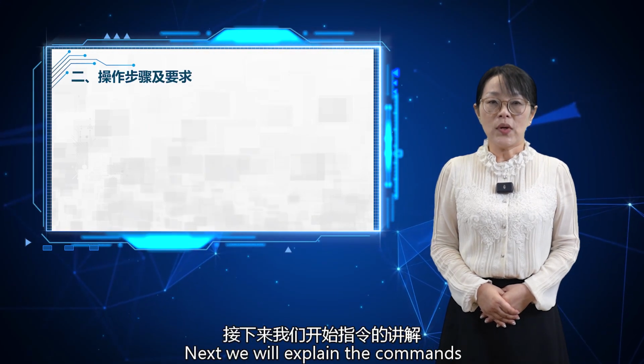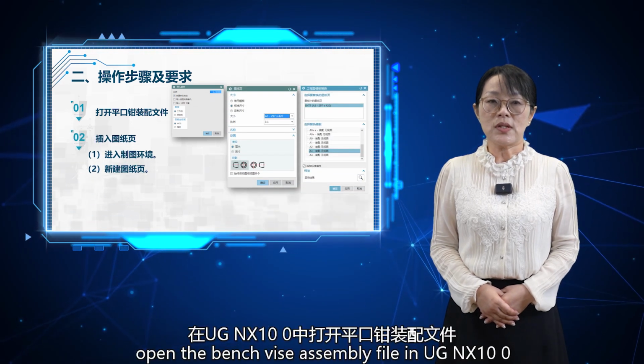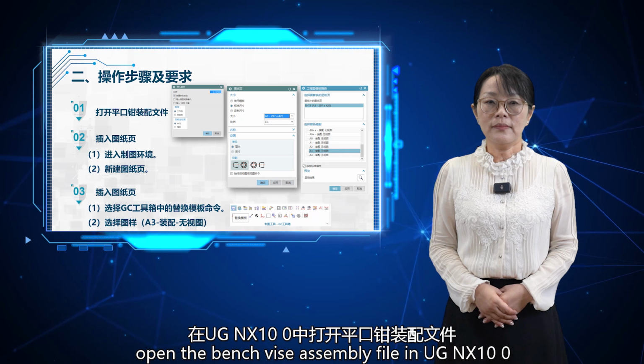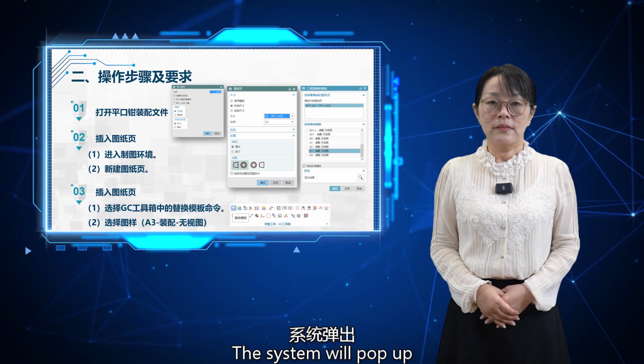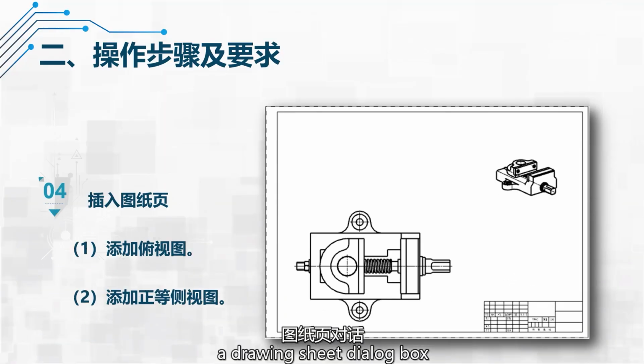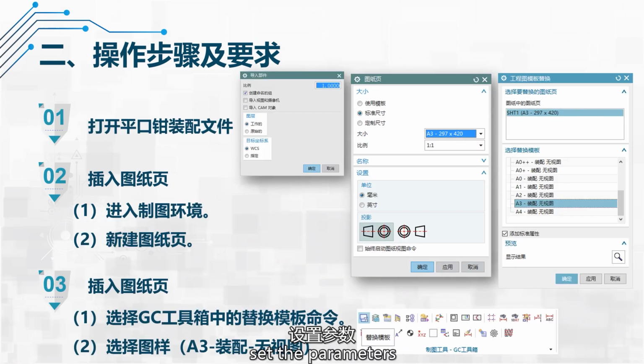Next, we will explain the commands. First, open the bench Vise assembly file in UGNX10. Then click Start Drafting in the menu bar. The system will pop up a Drawing Sheet dialog box. Select Use Template. Call the drawing frame. Set the parameters and enter the drafting environment.